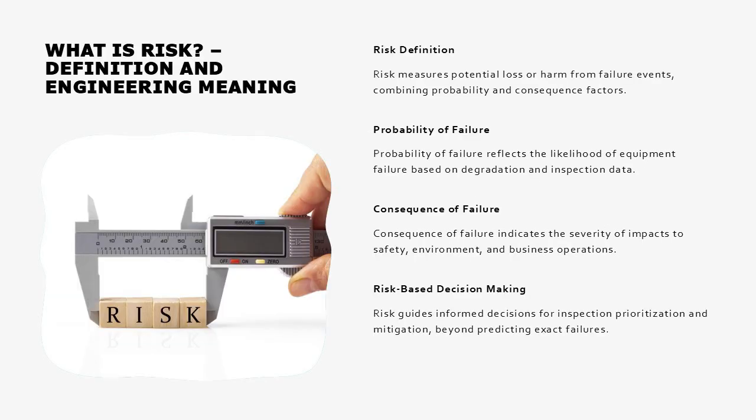In the context of API recommended practice, risk is defined as a measure of the potential for loss or harm resulting from a failure event. From an engineering perspective, risk answers three fundamental questions: what can go wrong, how likely is it to occur, and what are the consequences if it does occur.